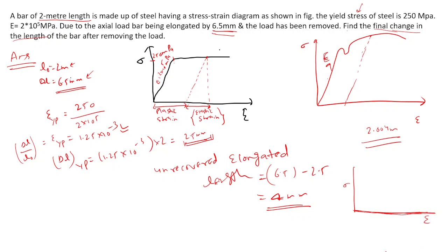Okay, yes. So sir, how can the elastic strain come after the plastic strain? Not getting what you are saying. You have drawn the elastic strain coming after the plastic strain. No, it hasn't. Actually, what happens? You took one rubber band. You stretched it, and it became this much length. When you remove it, it will come back, right? Yes, sir. It will come back, but if you now take the rubber band, stretch it very long, and remove it, again it will come back, but may not be to its initial position, somewhat less, right? Yes. The same thing happens here.